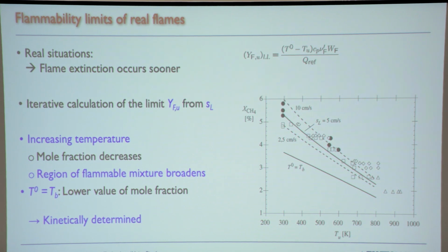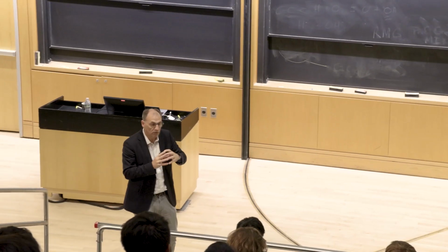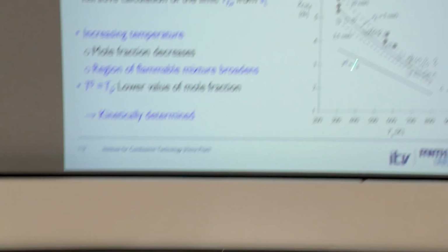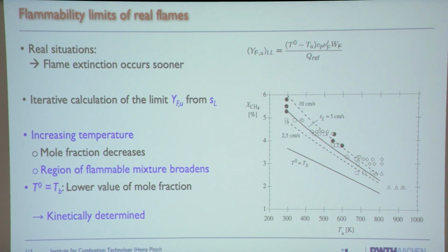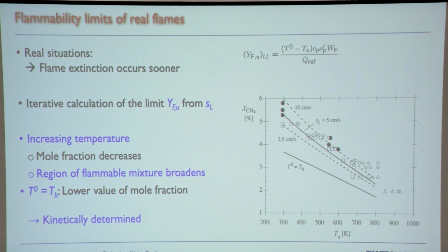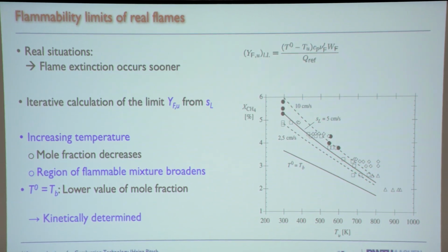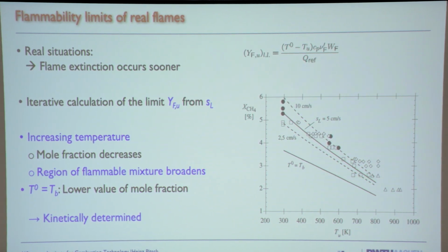Of course, when the flame becomes slower, maybe stability and inhomogeneity are also an issue. I mentioned the stretch effects. When you ignite this, you have a very high curvature in the beginning. For methane, that would actually make it burn more slowly. That would also bring it closer to this line if that were considered. And then radiation also plays a role, especially when flames go towards the limit. They burn very slowly, and then radiation becomes important, because radiation is also a slow process, and if the flames burn slowly, then other slow processes become important.